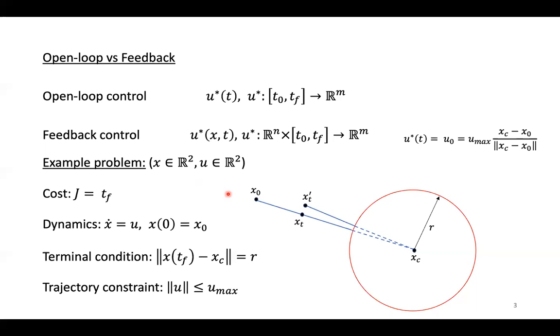So if you want to automate this process, and if you want to have a general control that would give you the optimal control at every state that you would visit, then you would write it in this form, which is a feedback form. So at a given state, you would choose u of x, which is in this form. Instead of saying I would pick this control regardless of the state, now I can write the controller as a function of the state. And in this case, you don't need time, because I think this is a stationary system, so the optimal control is not a function of time anymore. So that is the whole idea of feedback. Given any state, what is the best thing that I can do?